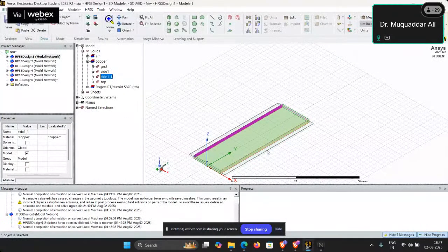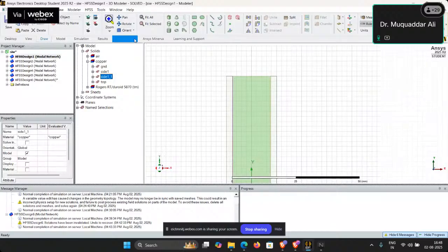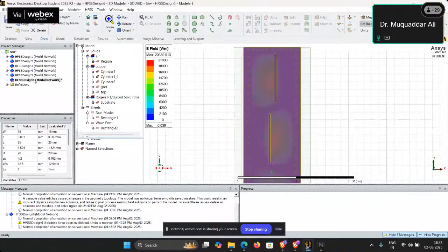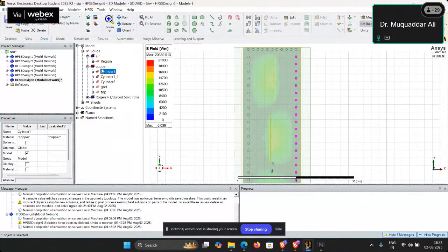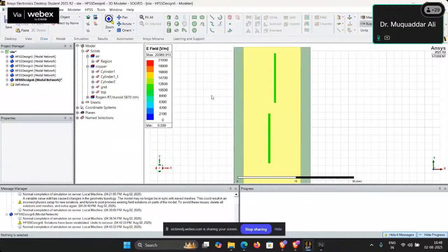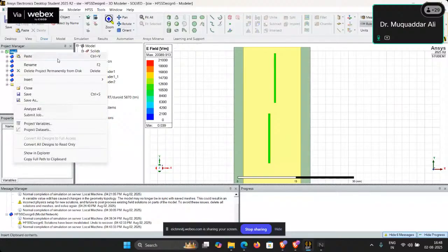So they will be slightly outside. So we will have a broader waveguide there than the original one. So, this is the first method, in which we add the slots in the waveguide. Another method is we can create cavities. In cavities, we have waveguide back cavities, cavity back antennas for rectangular waveguide, and we can implement them in our SIW also. So, what is a cavity back antenna?